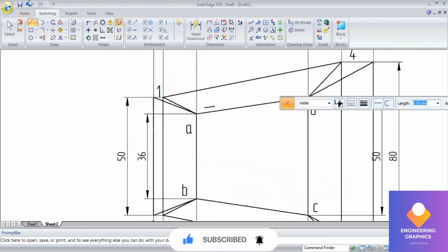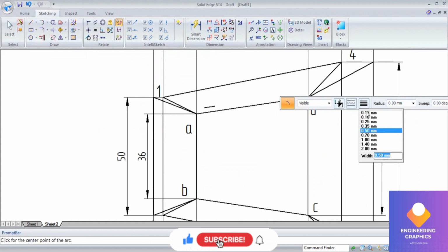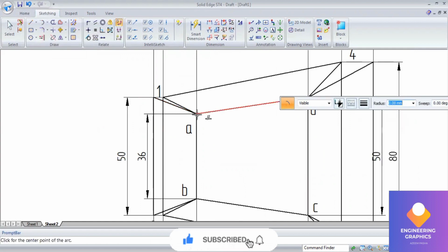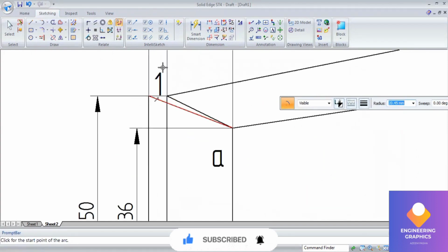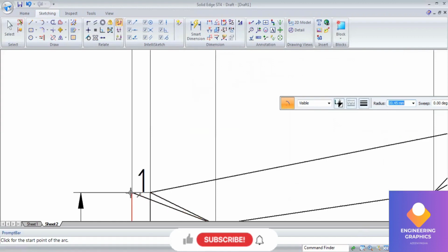Now you use arc by center. Go to arc by center, measure the line from A to that intersection point. Yes, this length you can measure. Take a reference point and measure this length from here to here and cut the arc. Yes, sometimes you won't be able to get it exactly here. Zoom in and try to connect, then cut the arc.